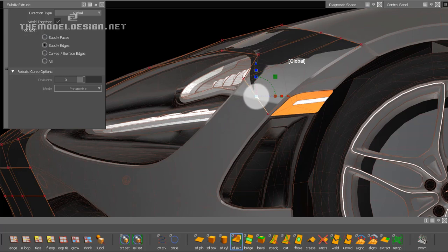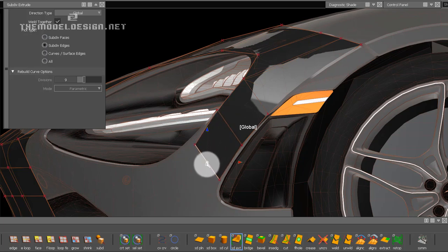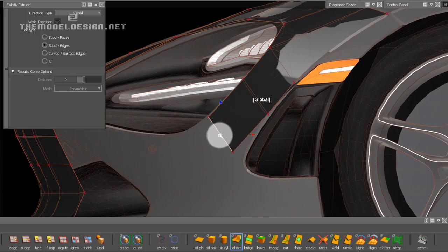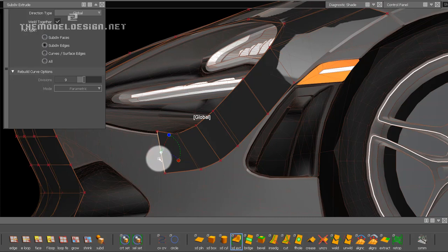Okay, so you can see that I'm still using this transform tool. I'm picking the edge, I'm moving the edge in the direction I like. I can rotate, I can scale, and I'm slowly moving on. I'm trying to keep my CVs perpendicular. It's not always possible, but if there is a chance of achieving a better CV layout, I will go for it, and I will take my time just to make it just a touch better.